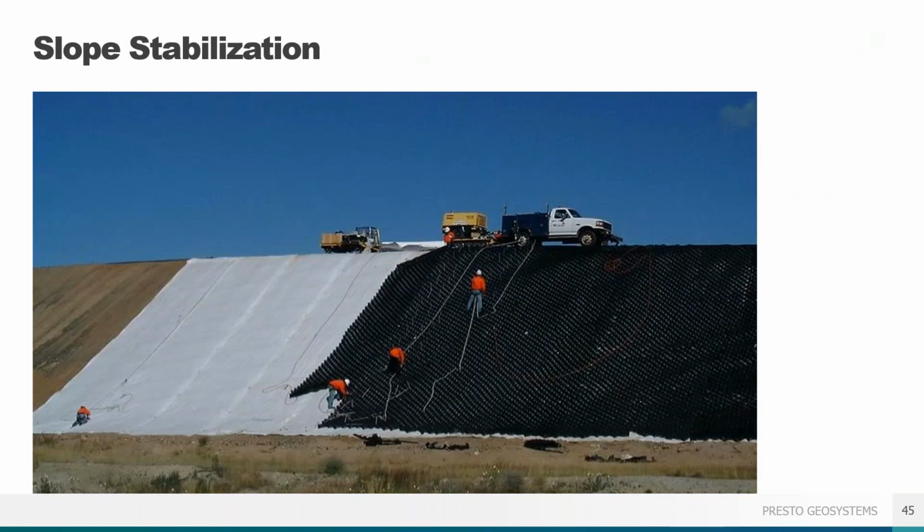So here's an example of a railway slope project in Montana with the use of ATRA anchor stakes. Aggregate infill was chosen for both sides of the embankment for erosion control plus a low maintenance slope cover. This project shows the benefit of material delivery at the top of the slope, greatly reducing the handling and truck traffic into the surrounding areas. When such delivery at the top of the slope is possible, it makes for a faster, safer, and easier installation.